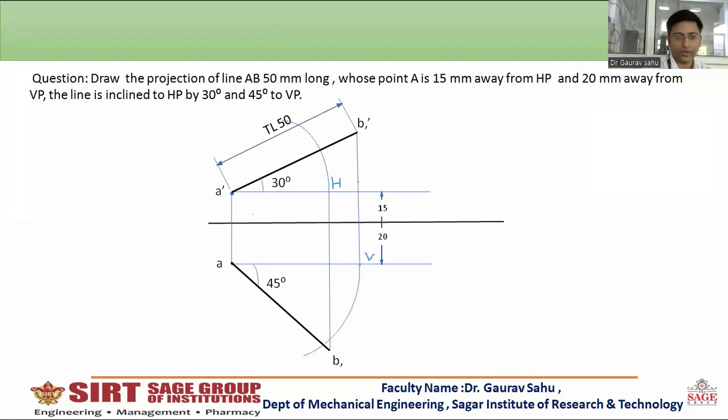First step, draw the projection for the two length at 30 degrees. Second step, draw the 45-degree angle, and simultaneously you are doing the projection of points. Step number 3, draw the vertical from both the sides to the locus of the other side. And step number 4, draw the arc in the similar manner which I have taught, A dash H and A dash B. So now step number 5, draw the locus from B dash 1 to cut this arc.